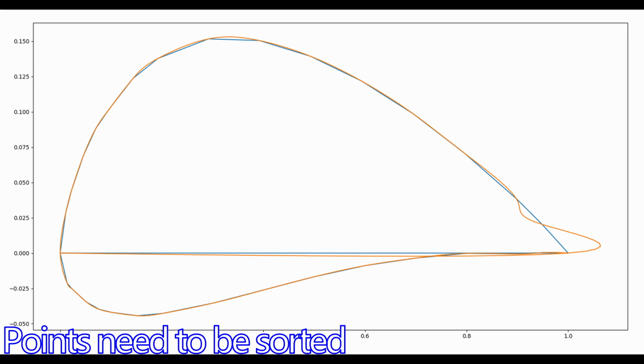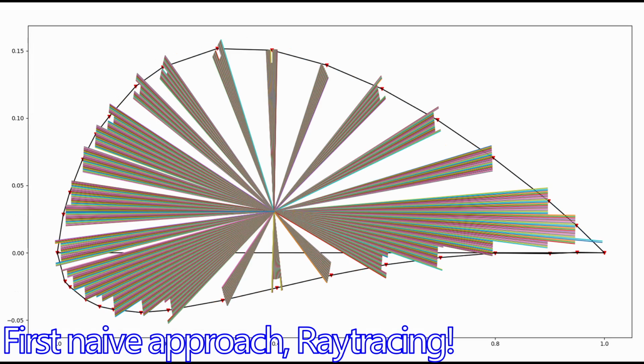So when I started on this, I first started on doing the wings portion because I assumed that would be the easiest and the best part to start testing on. And what I quickly found out is that DAT files from databases like airfoiltools.com aren't necessarily always sorted in the same order due to the fact that there's multiple formats for DAT files. So the first order of business was to implement a sorting algorithm to sort points into a clockwise order.